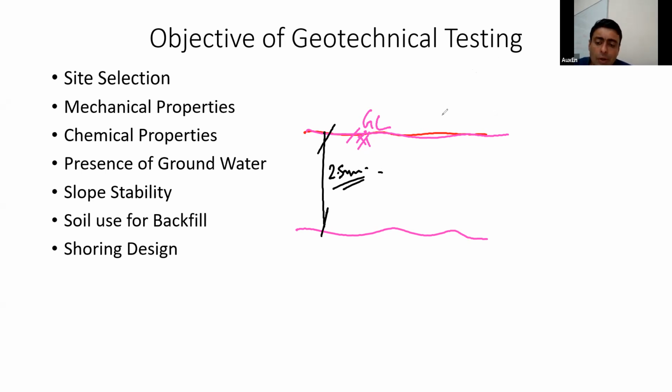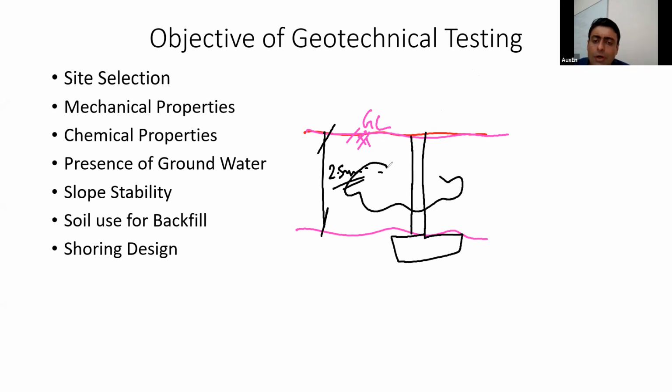So generally in Indore, you will always see that we will remove the black cotton soil layer. This is possible for buildings. Removal of 2.5 meters of black cotton soil is not that bad, because this soil is actually very good for agriculture. So then this soil is sold to landscape people, those who are going to develop some landscape, or those who are going to develop some gardens, etc. This goes for a very good price actually. So removal of black cotton soil is a good option for buildings.